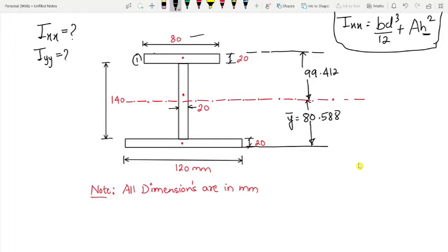We have 3 sections here, the first, 1, 2 and 3, geometrical rectangle sections of different areas that we have already seen. So we expect 3 distances, H1, H2 and H3, from the centroidal axis. Very careful: the distance between the centroid of area A1 and the centroidal axis is your H1.